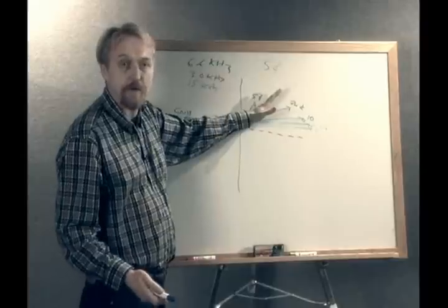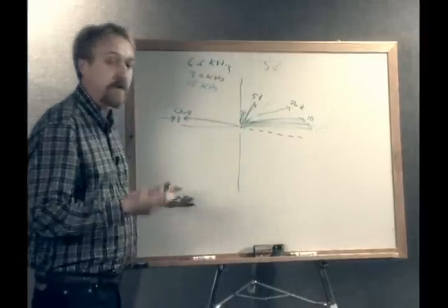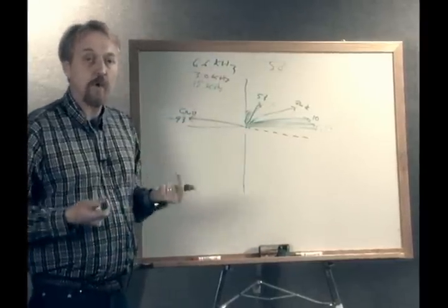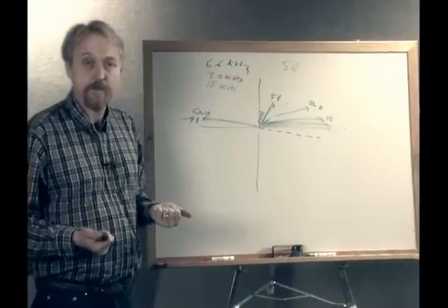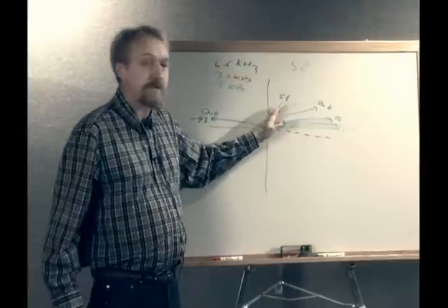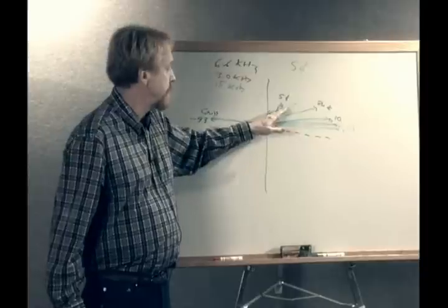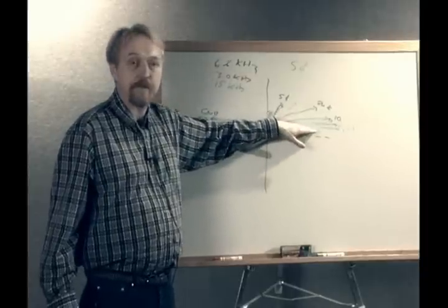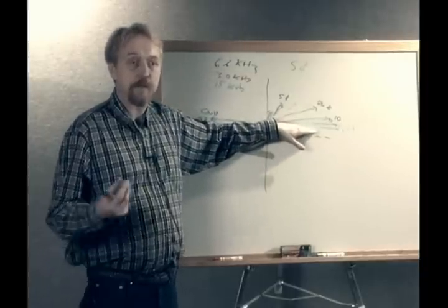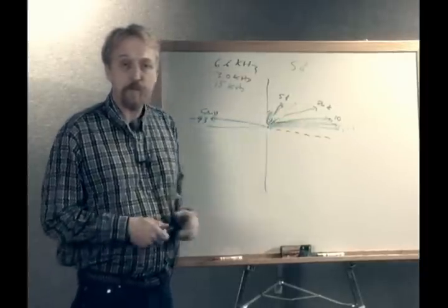Easier to tell them apart. So what you can see from all this is that there's clearly no one frequency that's best for all applications. Higher frequencies in general are better for smaller objects, less conductive objects, and lower frequencies give an advantage on things like copper and silver coins, large, very conductive objects.